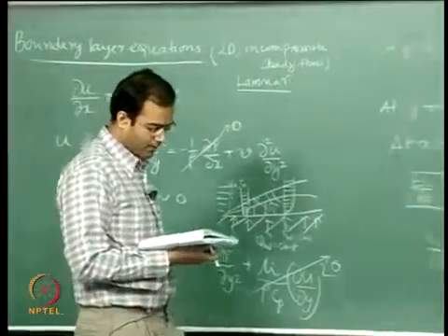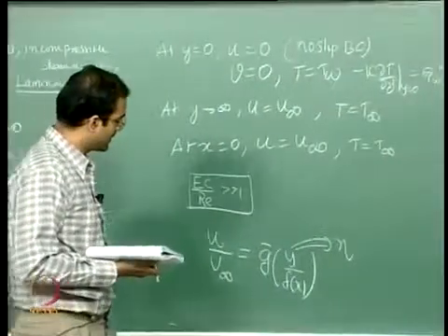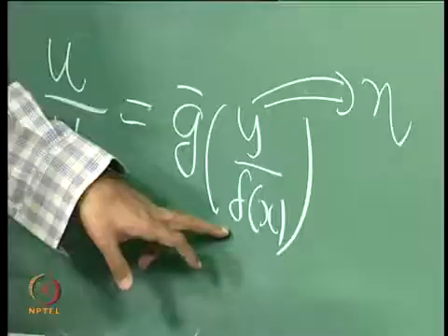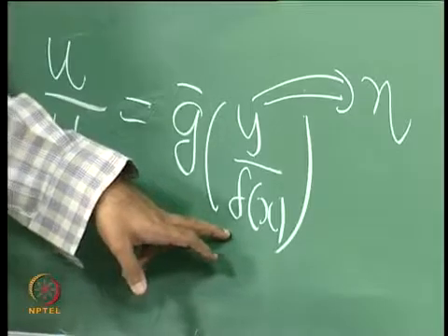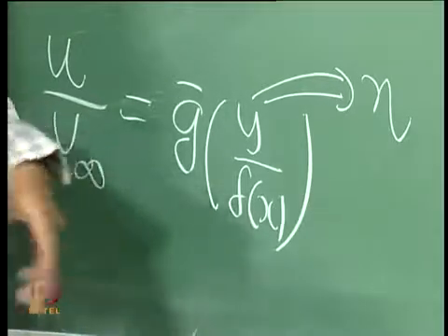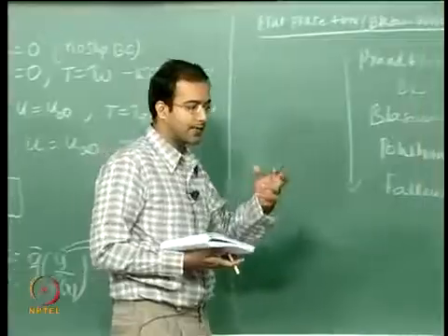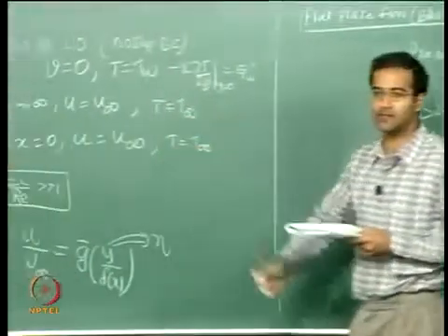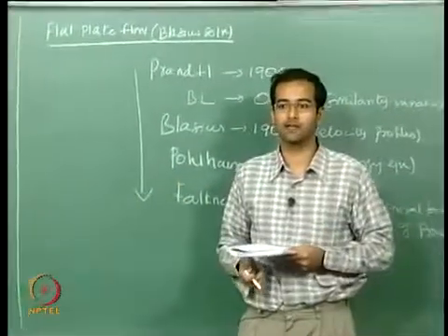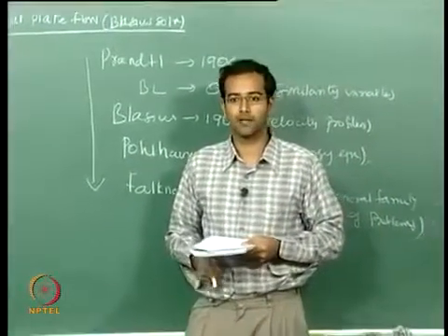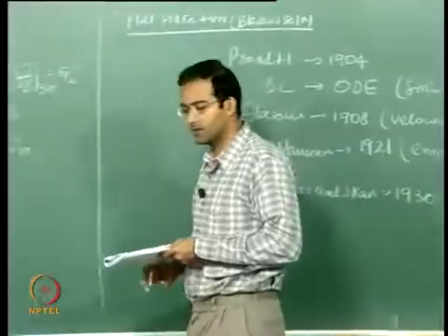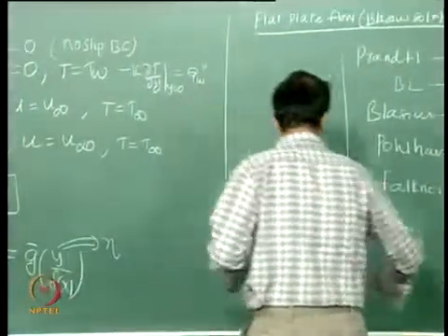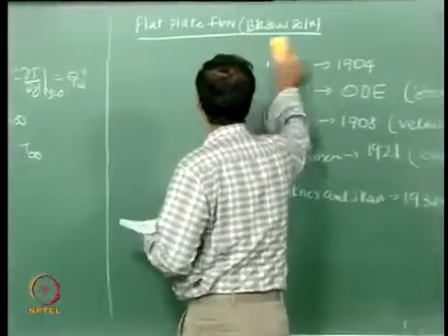Now, how he obtained the relationship between eta, y and delta: we should know how delta is a function of x. One way is to directly use simple scaling arguments like what Bejan does. Look at the inertia and viscous terms balance, and then you can directly get the functionality of delta. The other, longer way that I am going to do is helpful because we don't have to derive the same set of equations again. So that's what I am going to do now.